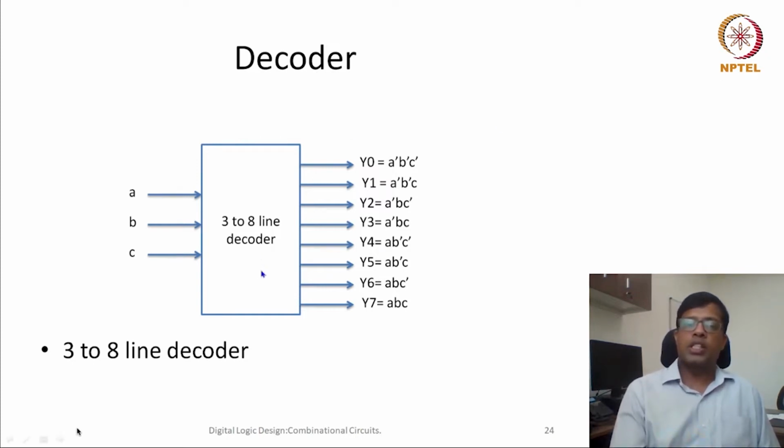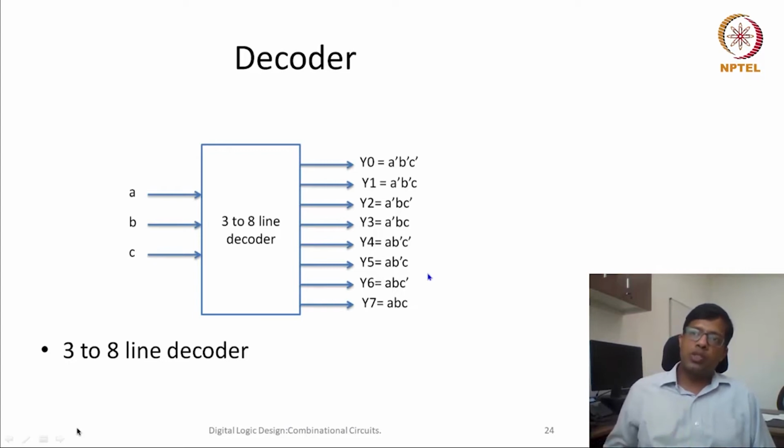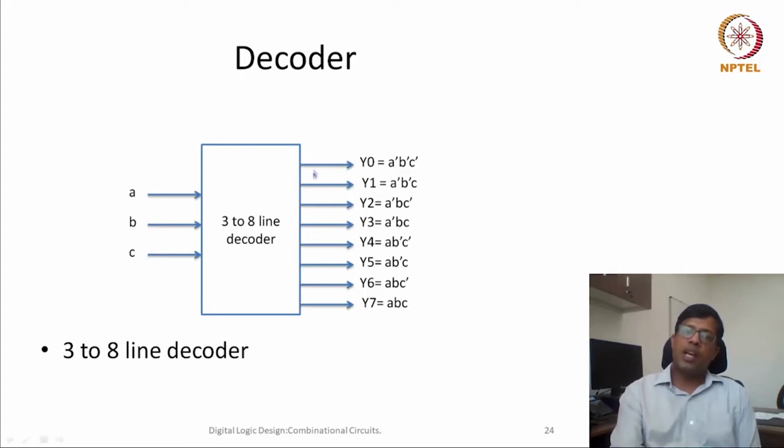So this is called a 3 to 8 line decoder, and you can see the purpose: you are decoding. Because now you have n numbers, you want to select which particular number it is. Let's say you have n LEDs and want to know which LED to light. If there are 16 LEDs, then only 4 bits are sufficient to know which LED should light. So this decoder can help us identify which number it is. Each number is represented as a different wire.